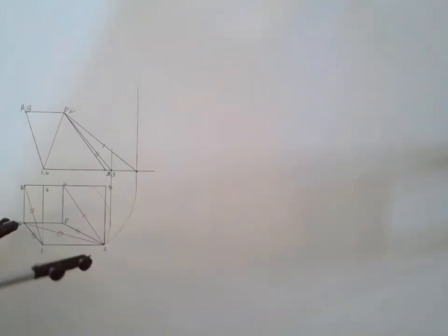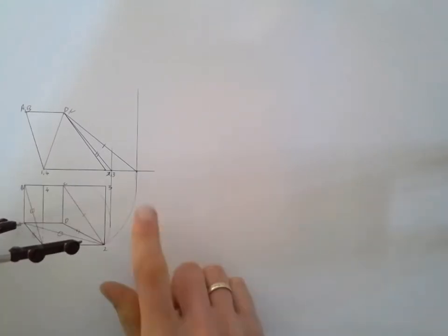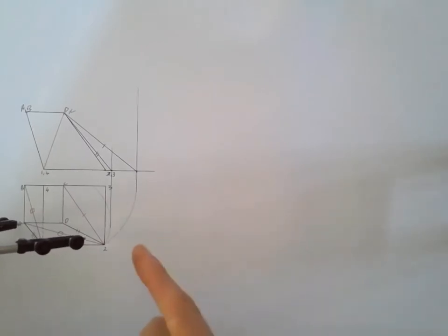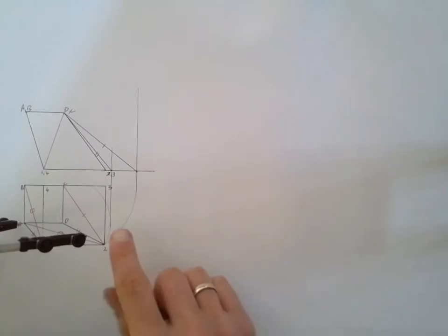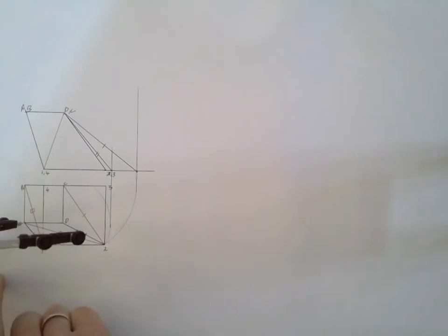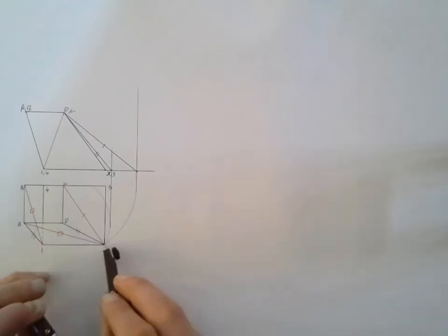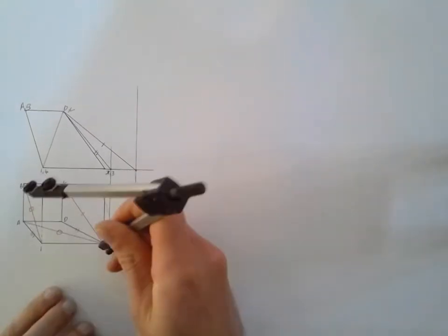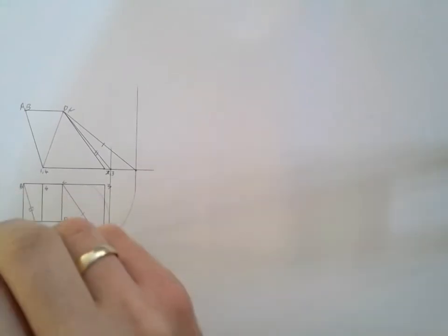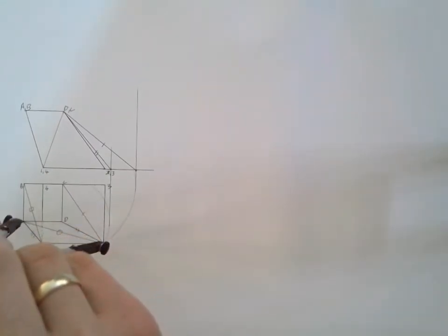Now, up until now I've been making an arc going upwards, but because I've already got 2 true lengths on this right hand side here, if I do another true length on that right hand side, it's going to start getting a bit messy. So instead of putting a true length on this side here, I'm rather going to try and get a true length on the other side of my drawing so things aren't too messy. So instead of putting my compass point on point A, I'm now going to move it and place it on point 2 instead. And I'm going to open my compass up to point A, so that instead of arcing on the right hand side, I can now arc downwards on the left hand side.